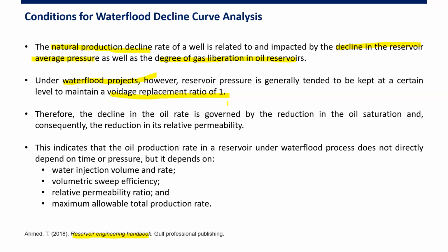Basically you want to maintain the voidage replacement ratio equal to unity. Okay, and by keeping VRR of 1, you will stabilize the reservoir pressure. You will make reservoir pressure relatively constant.